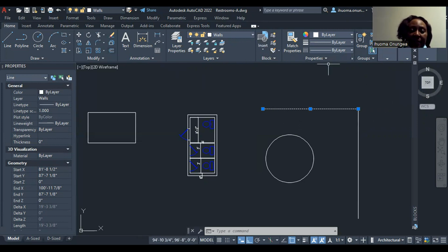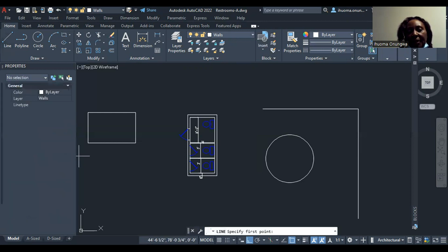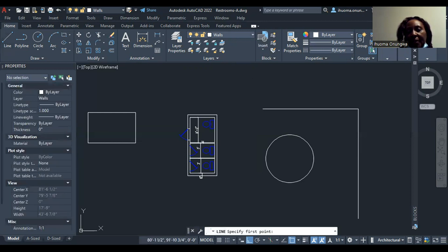So after that menu, you have your status bar in AutoCAD. And on your status bar, which is down here, you see your grid. And apart from your grid, you can put snap on or snap off. And then you have your dynamic input. What dynamic input does is that when it's turned off and you are drawing a line, you are not able to see any measurement.